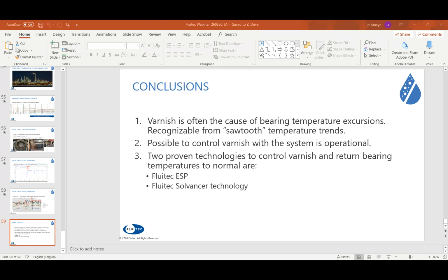If we used a solubility enhancer in the system, would that have any negative effect on the seals? No, because it will only enhance the solubility. It is not affecting any of the characteristics of the lubricant. All the basic characteristics of the lubricant are unaffected. We just increase solubility, so it will only be an enhancement, and certainly not have an effect on mechanical seals. We now have so many of these systems working with solubility enhancers, so absolutely not.